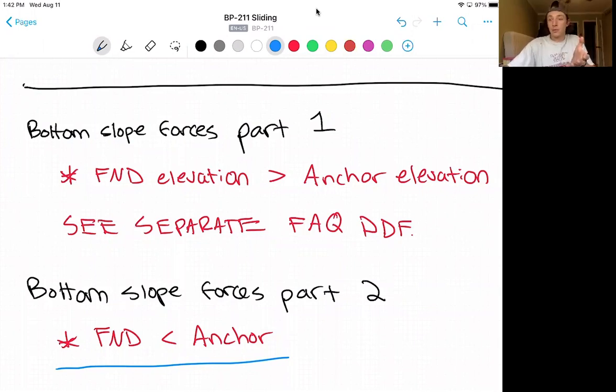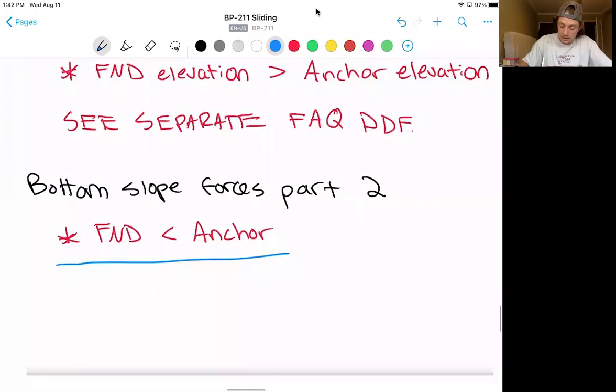That is, the anchor is going to use the ramp walls and fill to push the entire abutment uphill due to cable forces. We also have to assume a tension strut, which means the ramp walls and foundation, if on a downward slope, are going to pull the anchor downhill. Now, you may remember in the past, if the ramp walls hit the top foundation, we don't count the foundation weight because we don't want to account for that connection to hold all of the sliding force.